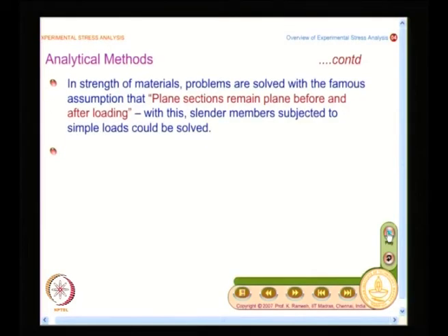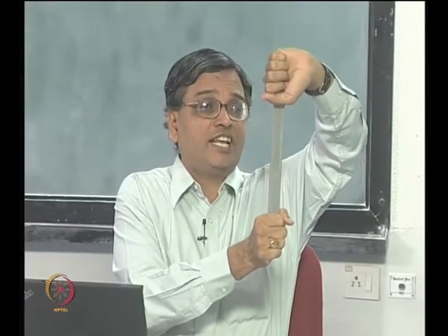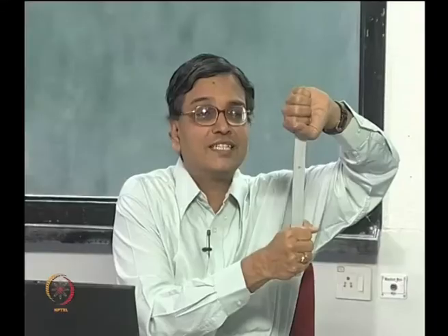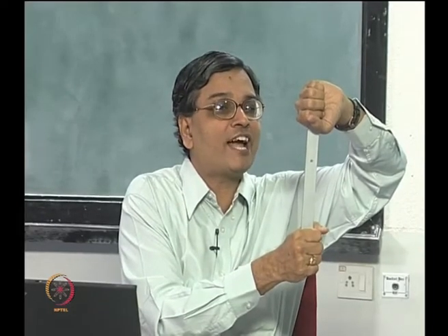No, what you want to know is the basic information that you use for attacking the problems. So one of the basic assumptions is that plane sections remain plane before and after loading, and with this we have solved a large number of problems which are slender in nature. It is very important. Suppose I take a plate and stretch it like this, I have no problem. Suppose I put a hole there, I cannot do it with strength of materials. The moment I put a hole, the assumption that plane sections remain plane before and after loading no longer exists.